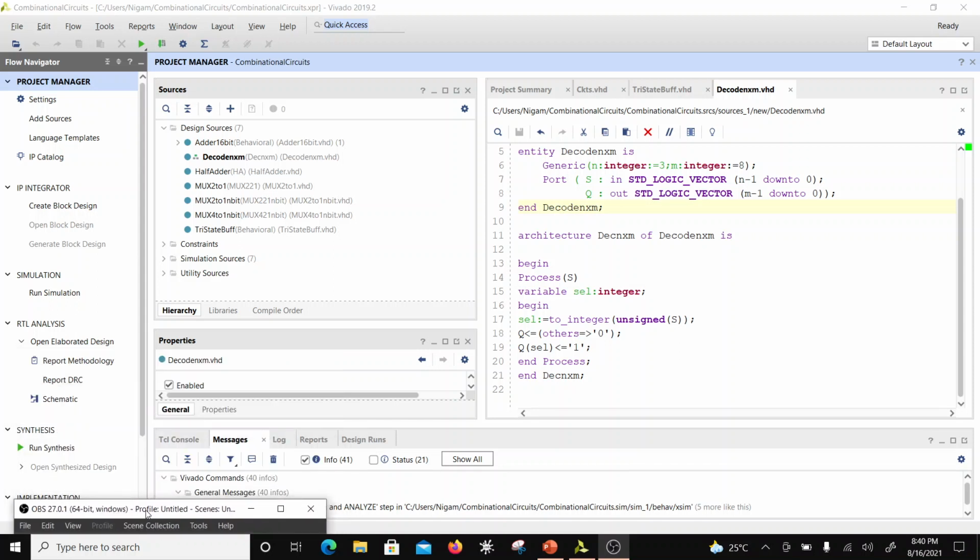So, well, there is nothing called sequential. Let me explain this. Anything sequential is basically constructed out of combinational circuits, which are not sequential, they are combinational, right? But then there is an element of delay, and by the time you feed back something from output to input, there is a delay and you lose the clock edge, so that state is maintained until the next clock edge comes. So that's how your flip-flop works, right?